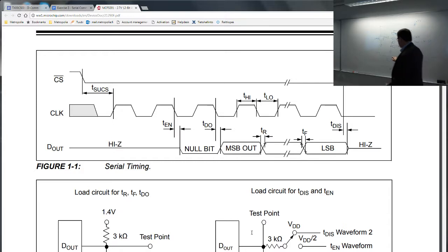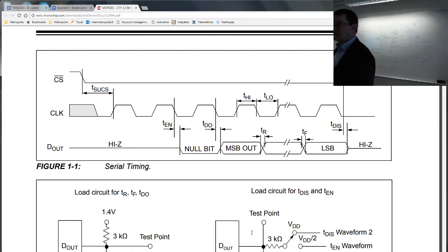Okay, but if we wasted 3 bits here, it means that the first byte you get from the SPI transfer is such that the top bit should be 0, and this is the 5 highest bits of the data payload. And then you have the second byte you read, which has the rest, 7 bits. And the last bit on this one would be whatever.